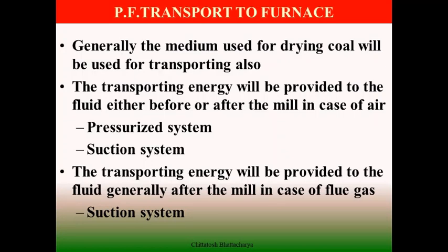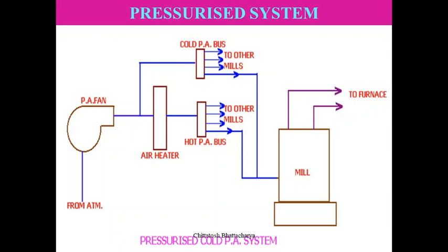The velocity is within the control regime, so that there is no erosion taking place. Neither should velocity be too low, which can cause chokage of the pipe, and that has to be avoided. So velocity within the coal carrier pipe is an important issue along with drying to maintain proper pulverizing as well as carrying the coal for the purpose of burning within the furnace.